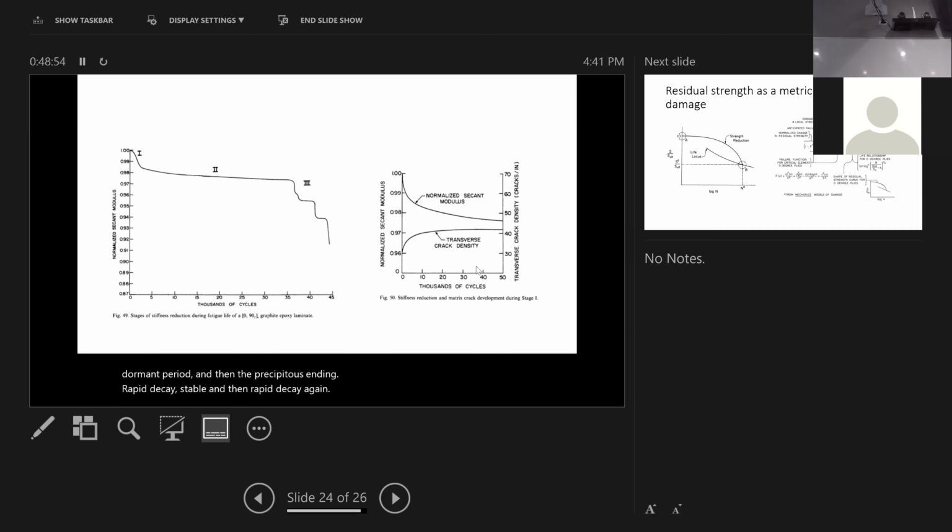Now people have tried to use a technique called acoustic emission to monitor composite structures. Have you heard about acoustic emission? Acoustic emission is when the fiber breaks, it gives off a burst of energy. You pull a rubber band, you pull hard, it breaks, and the rubber band springs out. It releases a little bit of strain energy. That strain energy sets off a wave propagating into the material. It's usually in a sort of acoustic range. It's an ultrasonic range, sorry. It's a several hundred kilohertz frequency.